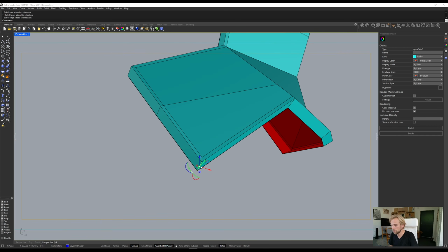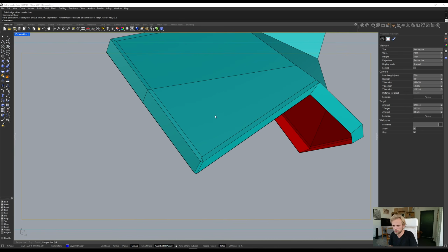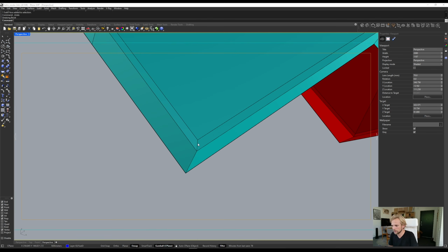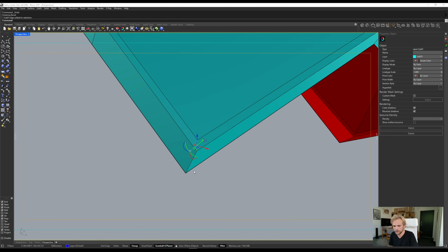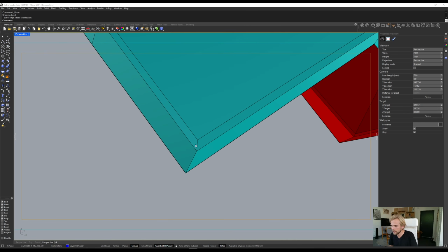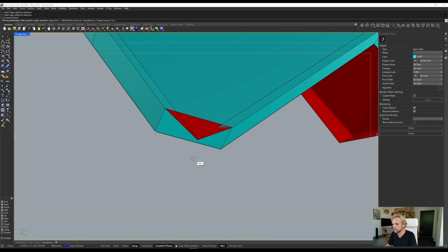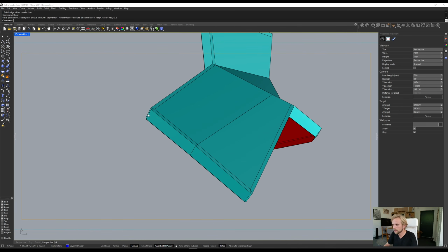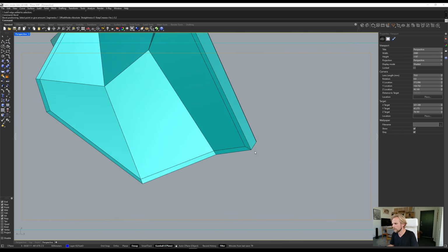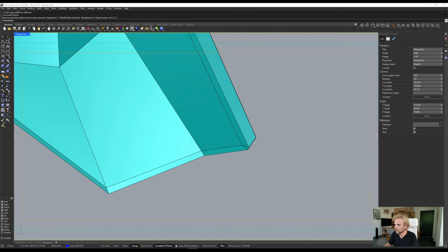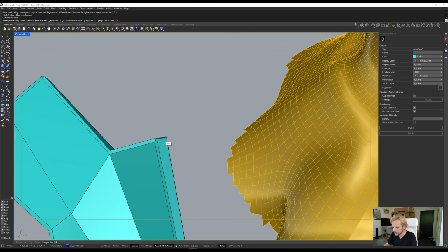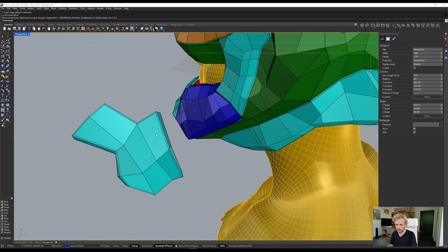And now, no matter what we do with the corners, bevel, 0.2, no matter what we do with the corners, this surface is going to be protected because that edge that we had here, this edge is eating up the bevel, right? So an edge becomes a triangle. Again, bevel, 0.2. So this is what we call protecting your corners, right? With the inset. Very useful little tool. Okay, so basically that is the idea behind it.